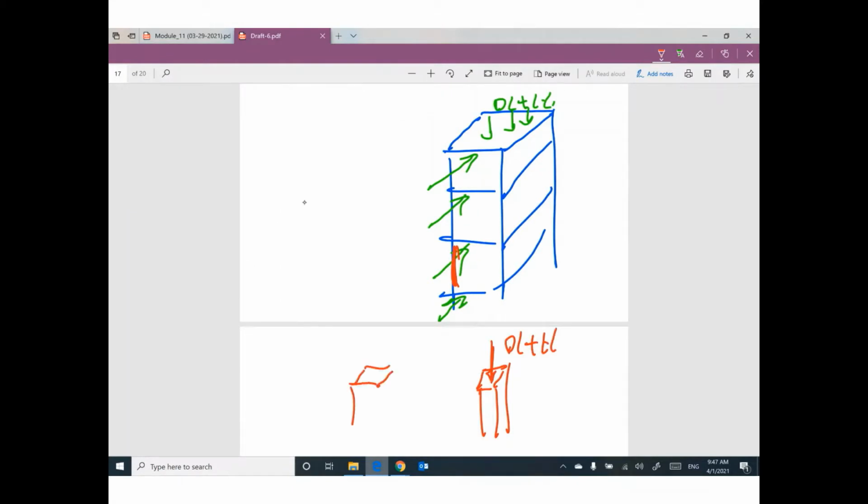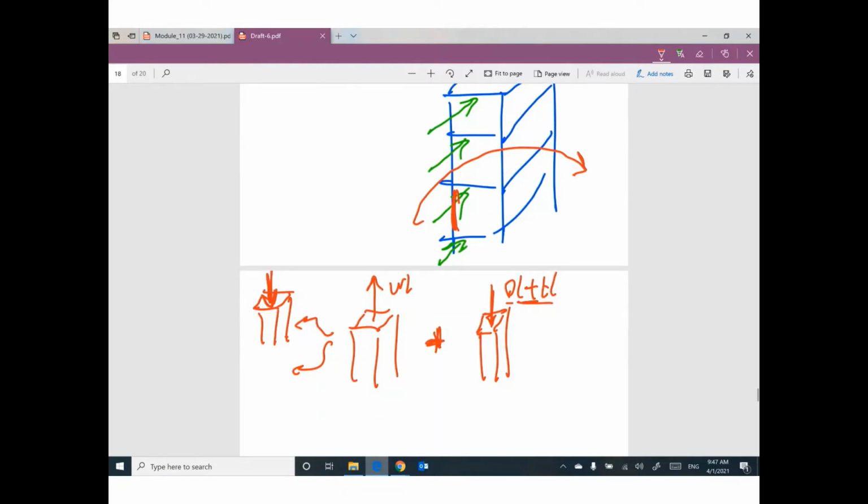However, the lateral load would like to overturn this building like this. We expect tension due to wind load or earthquake. If you make a combination of both of them, probably you have two scenarios. The first scenario, the dead load and the live load are bigger, so the final will be compression. Sometimes for a very high-rise building, the net force on the column will be tension.